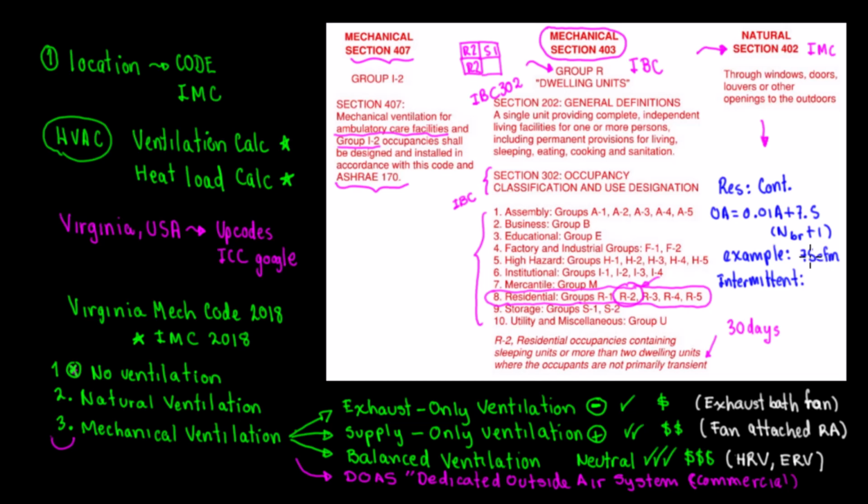When you put intermittent ventilation, and I have that in other videos too, then you have different requirements. In this case, this is the minimum. Intermittent is going to depend on the rating of the fan, maybe 115 CFM, so you have to check the cut sheets of the fan. Continuous is always lower than intermittent, and we always check for the intermittent ventilation, at least in residential. In commercial we can sometimes do continuous.